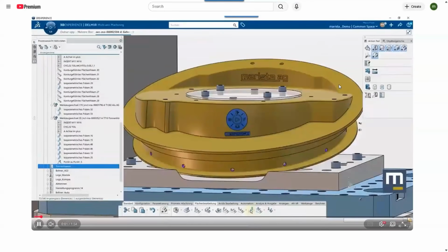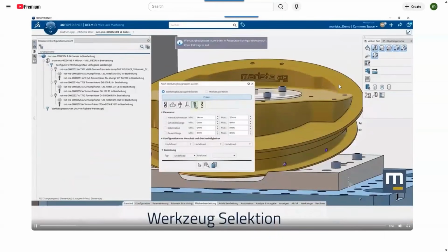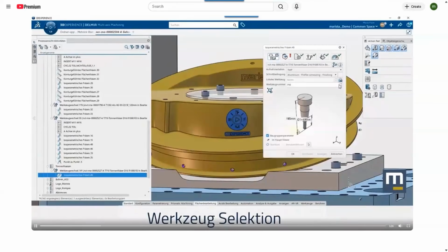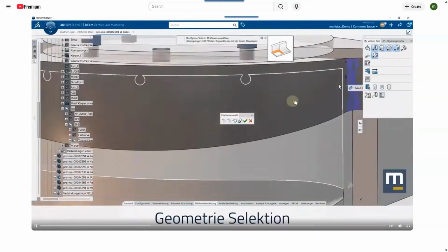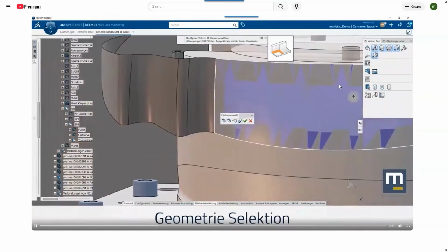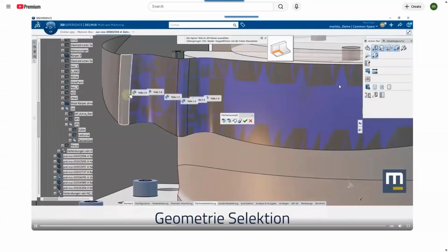When we start talking about advanced capability in our milling, then we unlock all of the capabilities that we have for being able to create advanced tool paths. This is an example of a barrel cutter that comes in any of them, but the ability to have specialized operations at the bottom for tube porting, for rotors and blades, for outside profiles, specialty things you would see in aerospace. We have the ability to program all of that and have special operations for it to make it easier to select and then build templates off of that. Here's an example of doing a barrel cutter on that face.